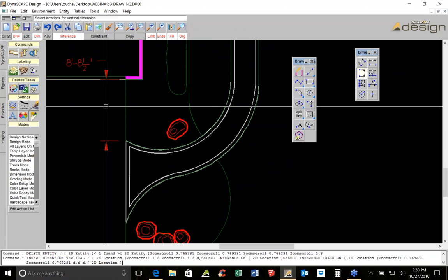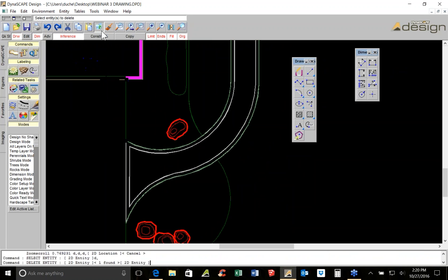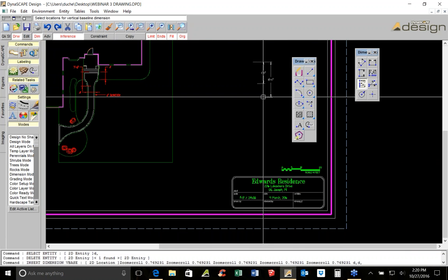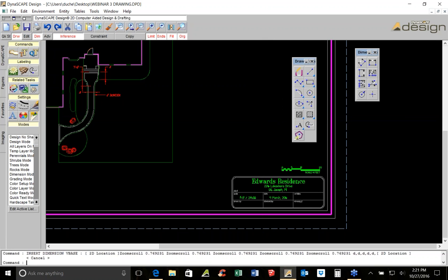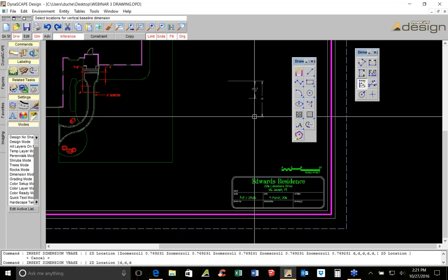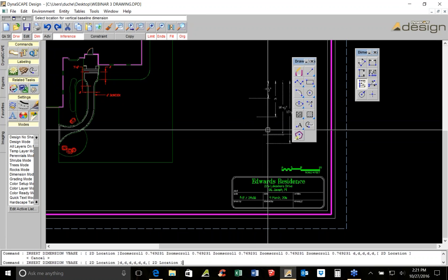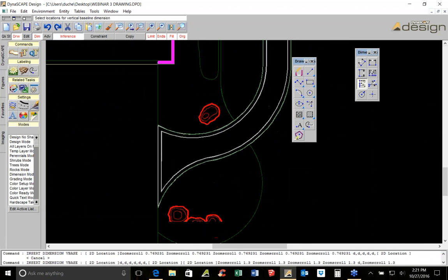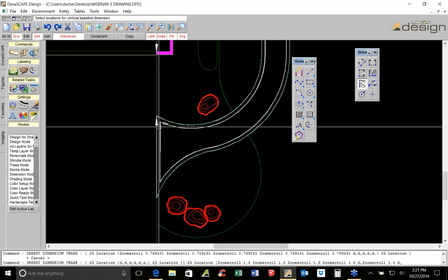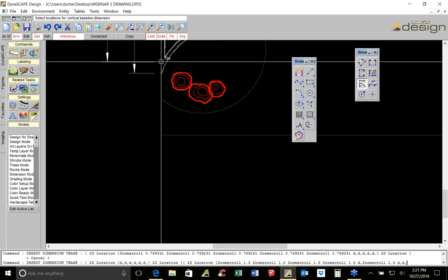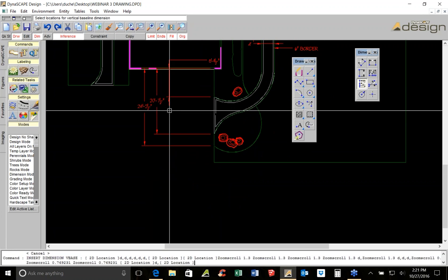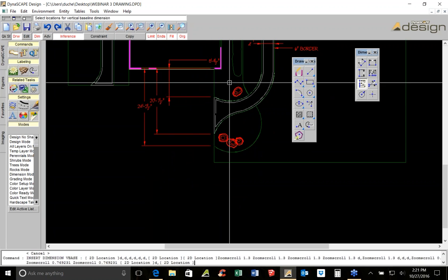Let's use a tool that's designed to give us a kind of rapid fire dimensioning. Check this one out. You ever seen these dimensions on plans? So we're going to click down from the garage to the first point, to the second point, and to the third point. We're going to drag this over and then left click, and it's there.